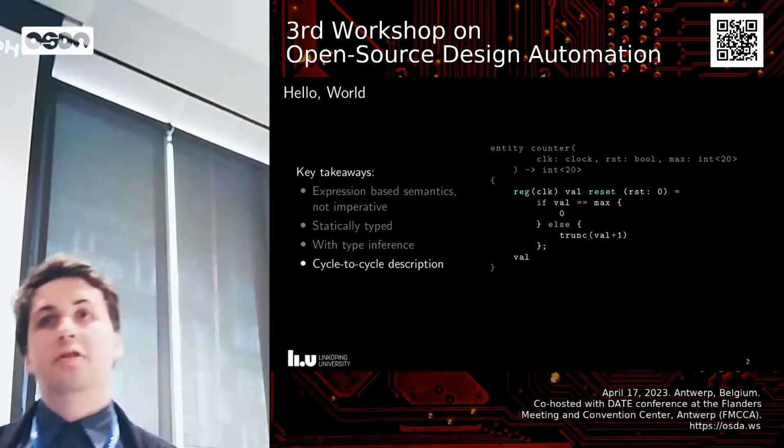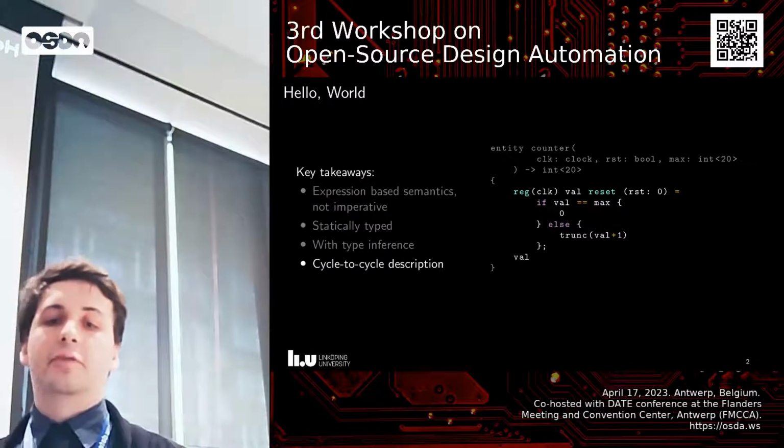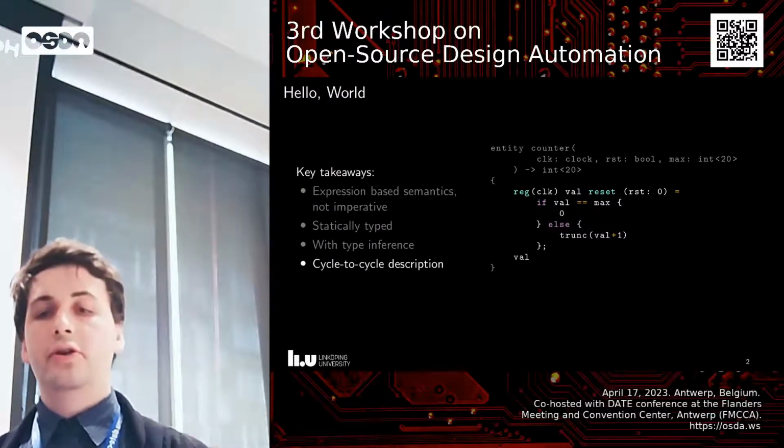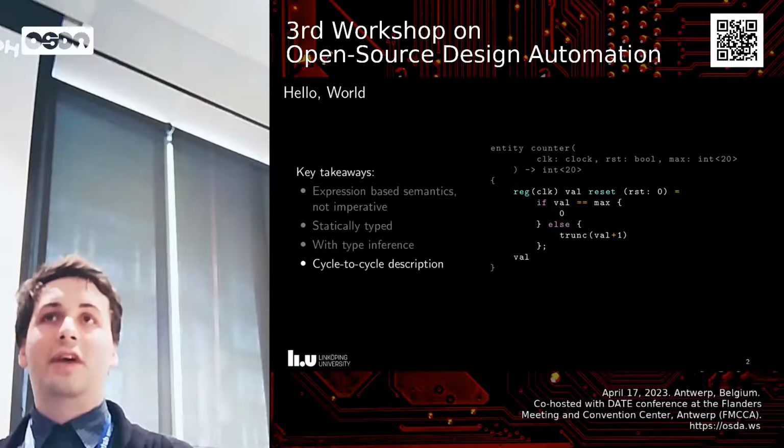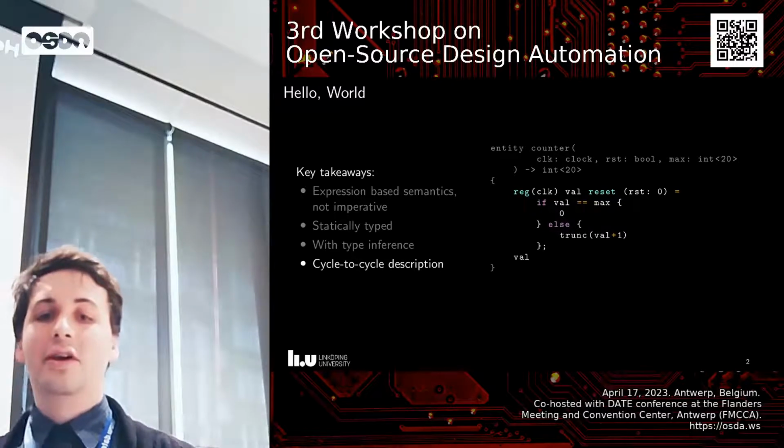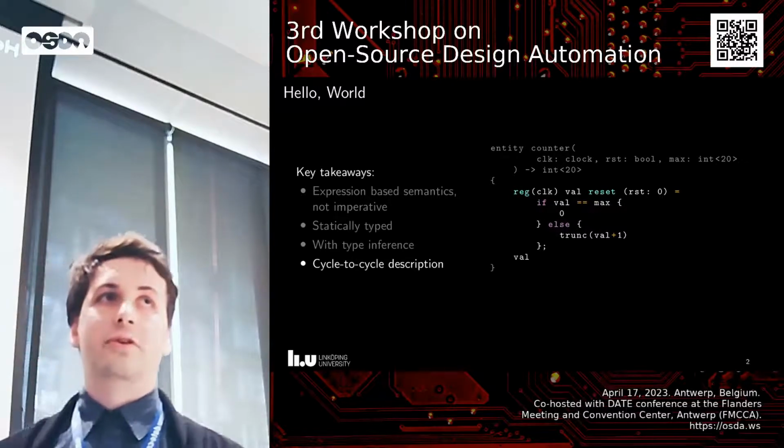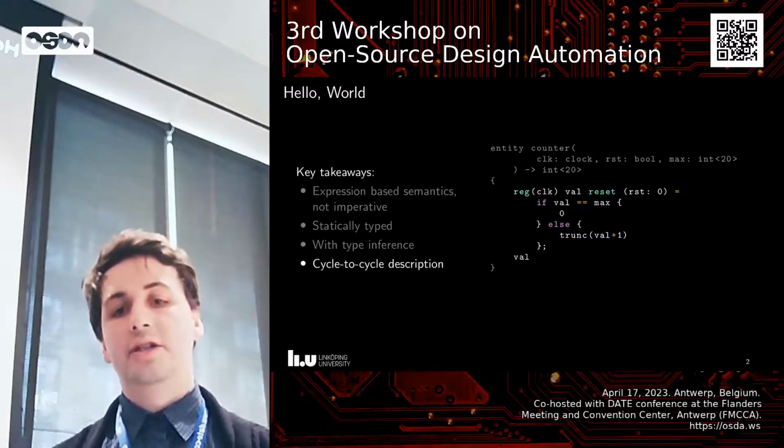And unlike BlueSpec, this is a cycle-to-cycle description of your hardware. You give the new value of all the registers as a function of the old value of all the registers, but you have a lot more structured tools for doing this than you do in Verilog and VHDL.